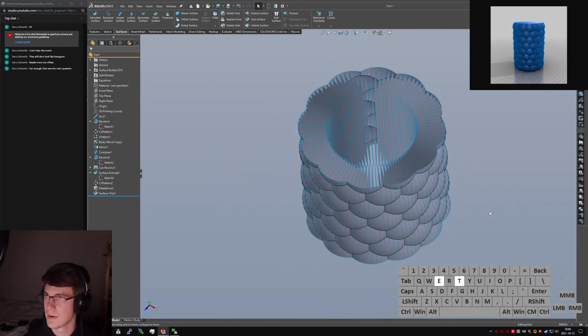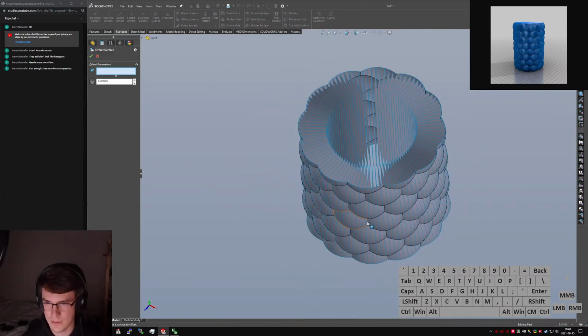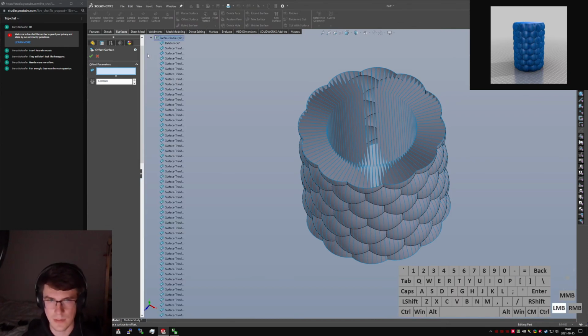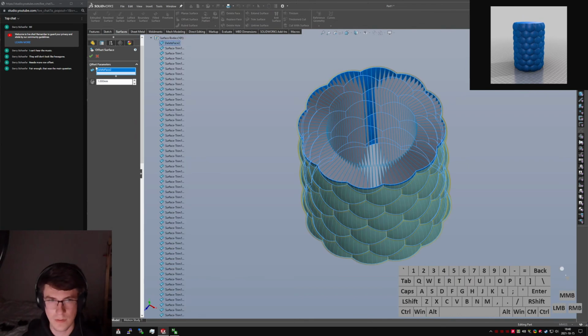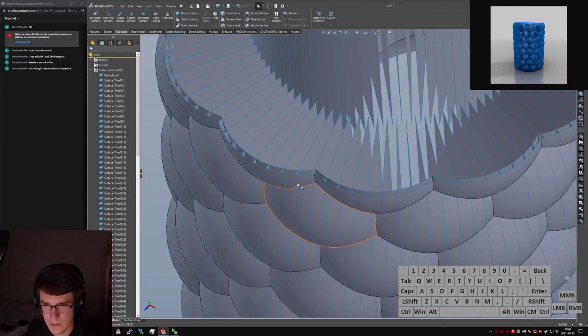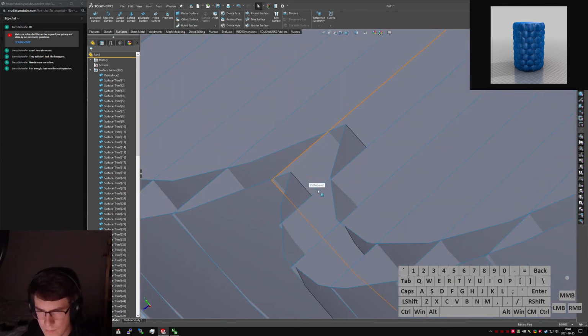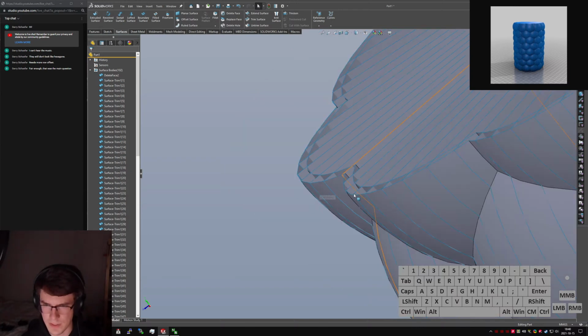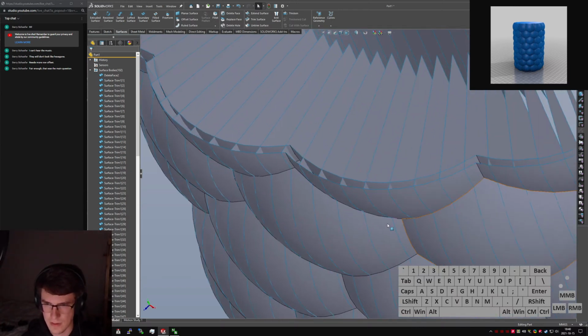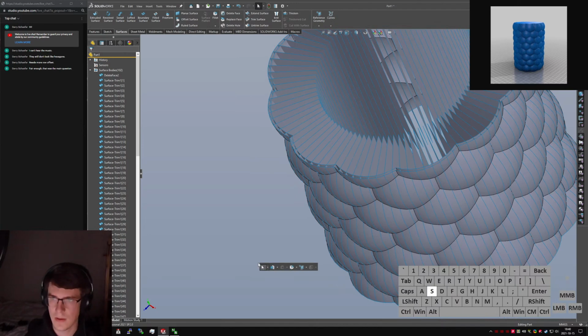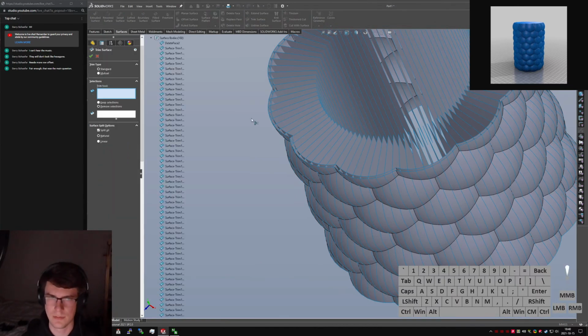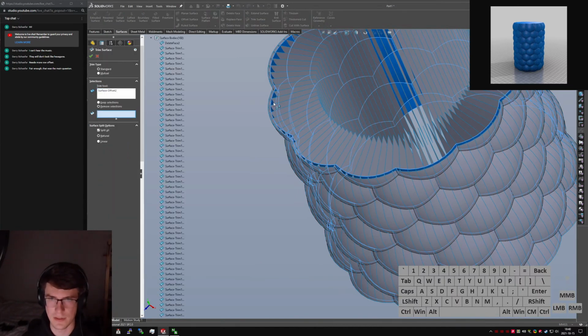Now, offset surface. Can I pick the whole of that guy? I can. We'll do a millimeter inward. Those look planar, which is good, because otherwise it would break a lot of things. Now we do the same step. Trim surface, standard, using this one.